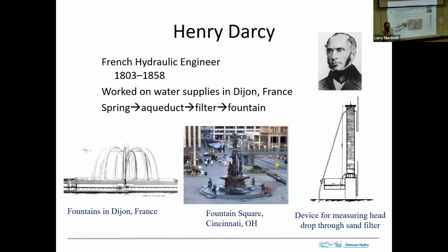So Darcy did this experiment. This is his apparatus. And you can see he's bringing the water in here, going into the top, and it's coming down. And then there's a little spigot there, and he's filling up that box, and he would get the flow rate. These are manometers, so he could determine the water level here and here, and get the hydraulic head gradient by taking the difference in the water levels and the distance.